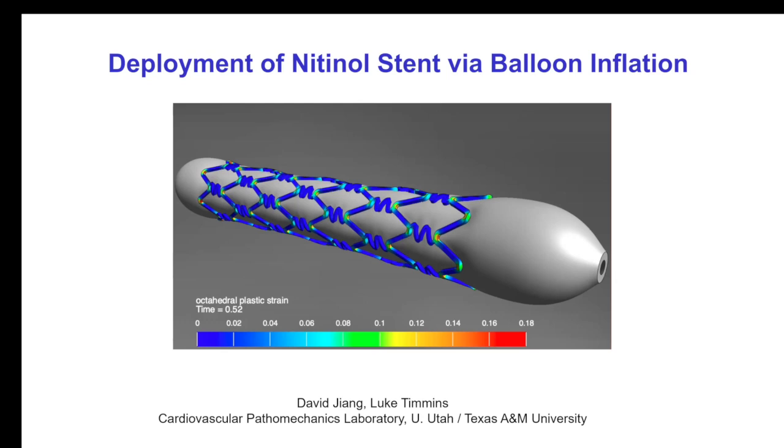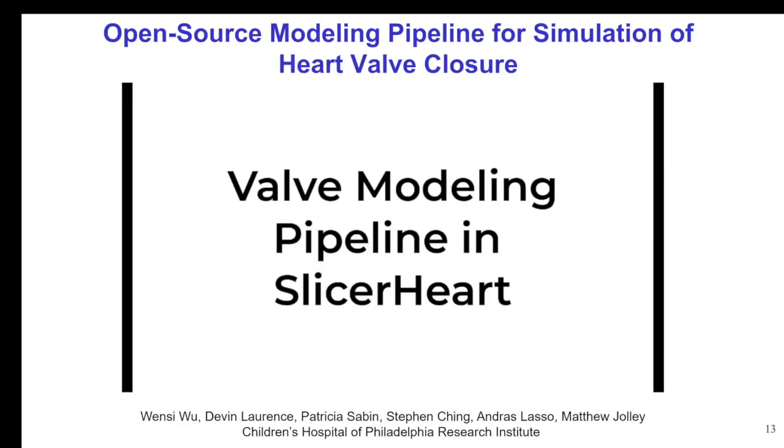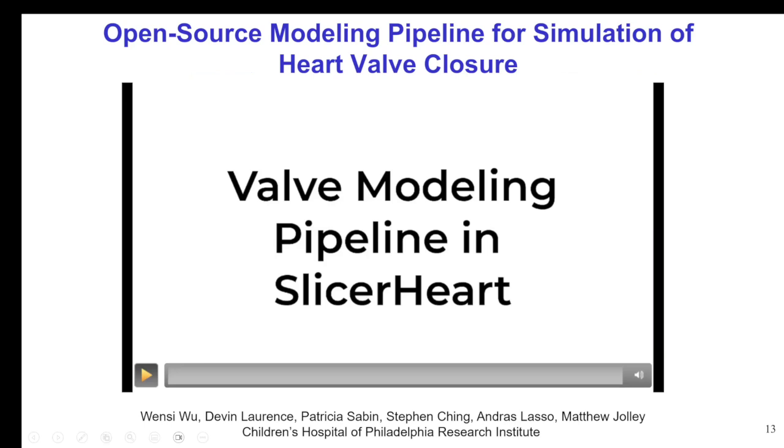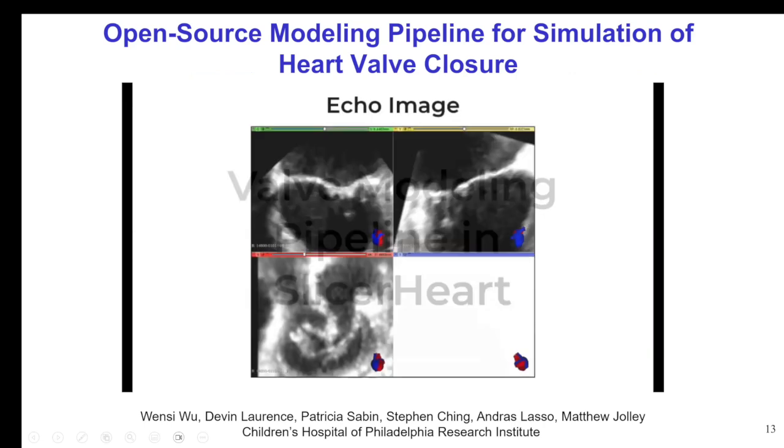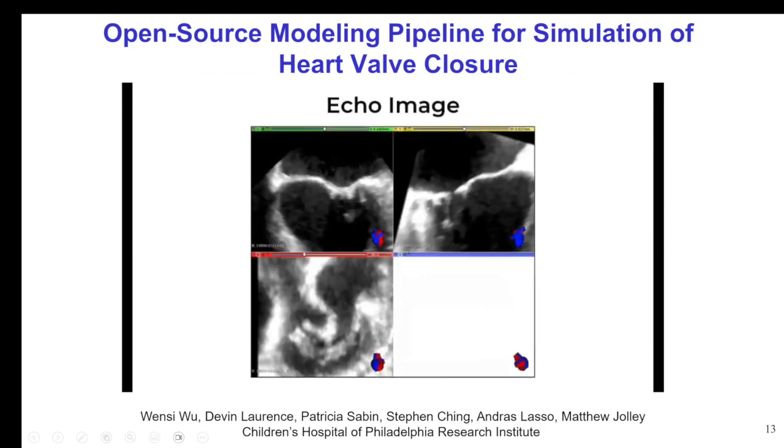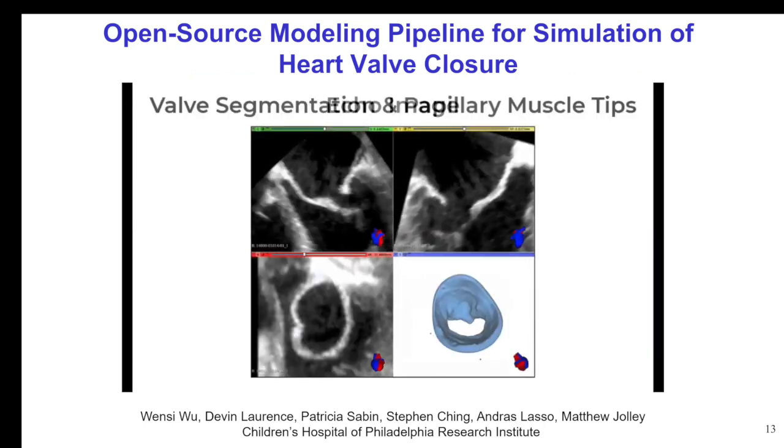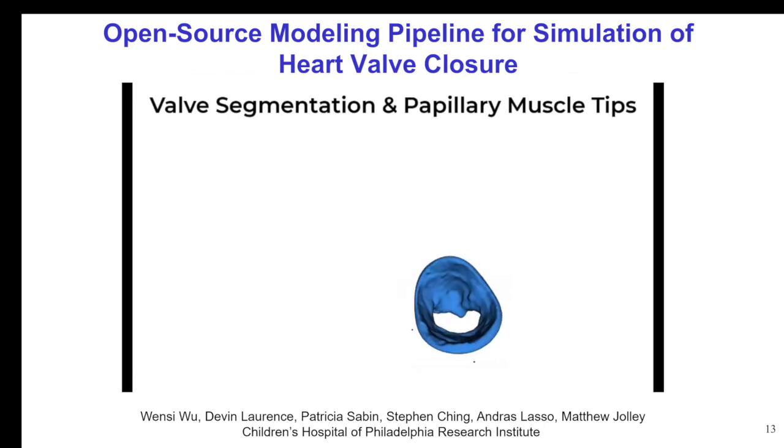Control the motion of the valves, and they perform the finite element analysis in FEBio Studio. And the idea here is to predict the closed configuration of the valve. And so this is a challenging contact problem, so we implemented a new contact algorithm for this. There are various metrics of valve function that you can examine from these analyses.